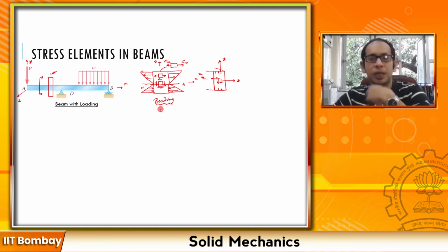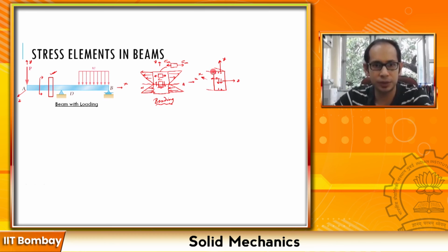Now, you see, it's a very interesting problem, in the sense that for the beam about the longitudinal axis, you have points within the beam. For example, at the top over here, the shear stresses are 0. The complementary about the longitudinal axis is also 0. So here you just have the bending stresses, whereas at the neutral axis, the bending stresses disappear. You have 0 stresses, 0 strains at the neutral axis, and there the shear stresses peak, right?